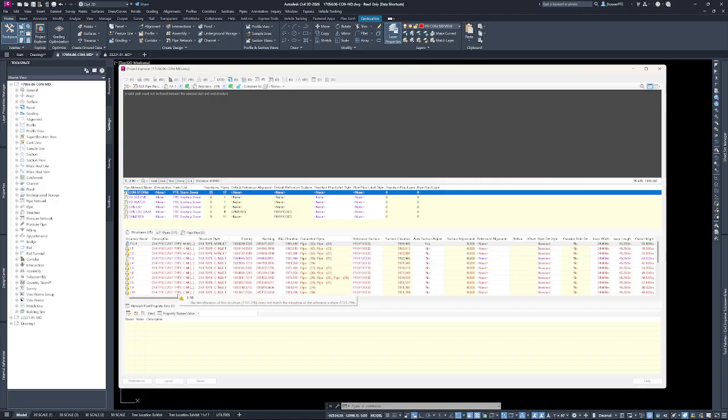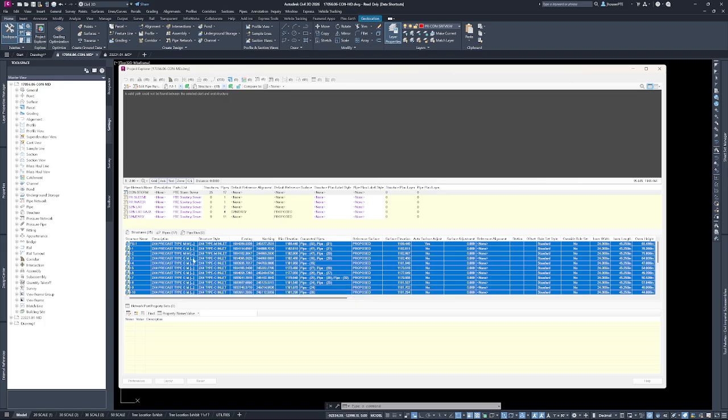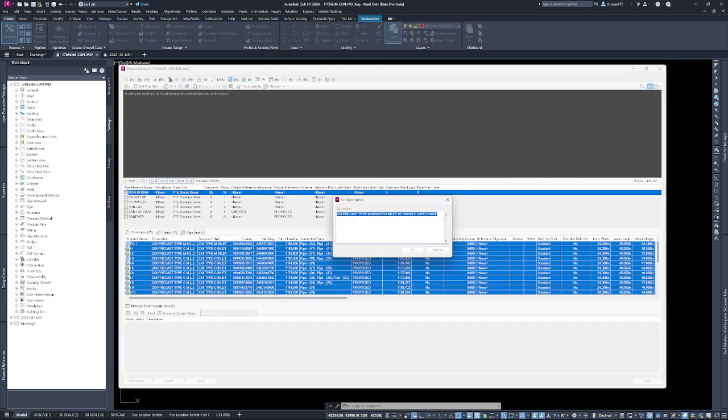I can select all of them, even though I probably shouldn't because I see there's M's and C's in here. You would go in here, type all that in one time, and you'd only have the inlets that you need changed. Type in one time and it would update them all. So that's a really important and quick way of fixing things rather than clicking on individual structures one by one and pasting them in that way.